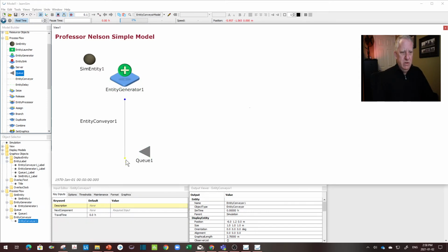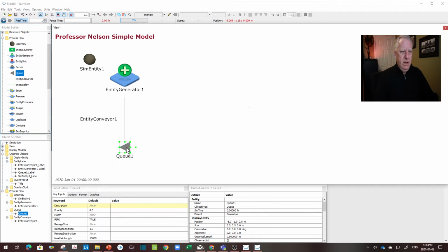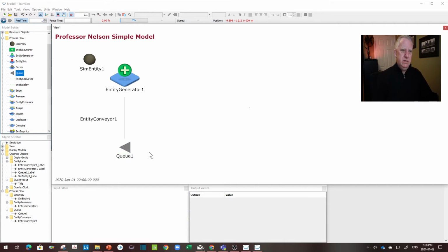Okay, so we've got material being introduced into the system, physically transporting on a conveyor, and I like to typically then bring material into a queue. Like, it has to go somewhere, and rarely does material get introduced into a system that goes straight onto a machine. It will go into some sort of a queue on a shelving or in a Kanban storage location or something like that. So that's what this queue is for.